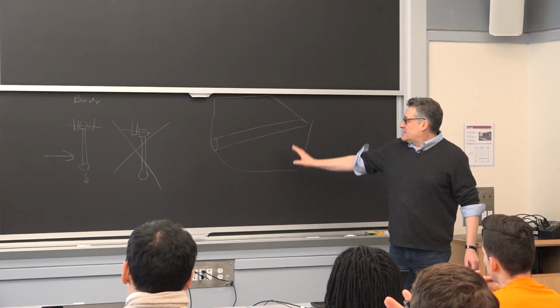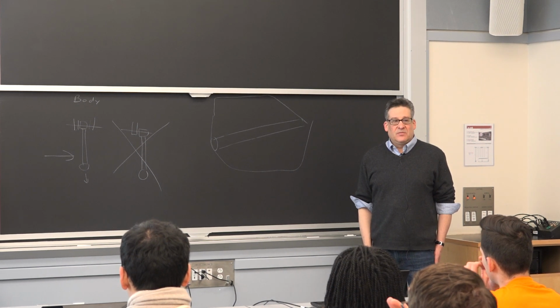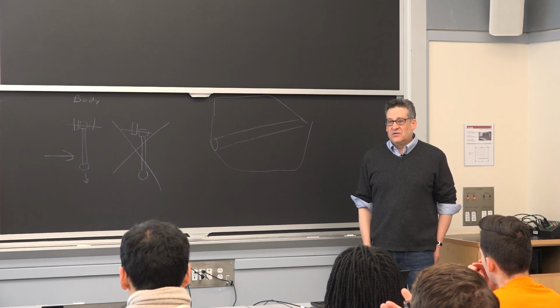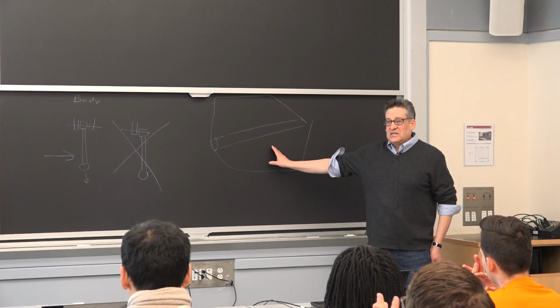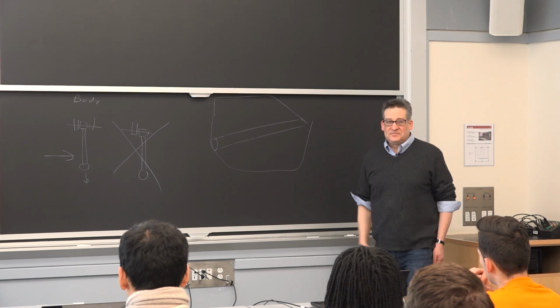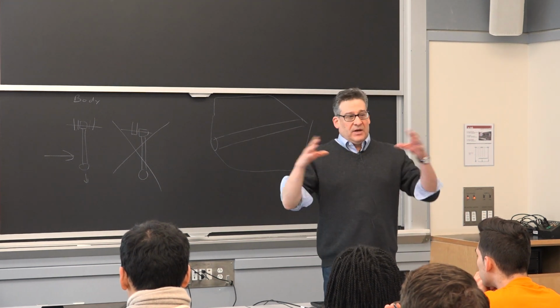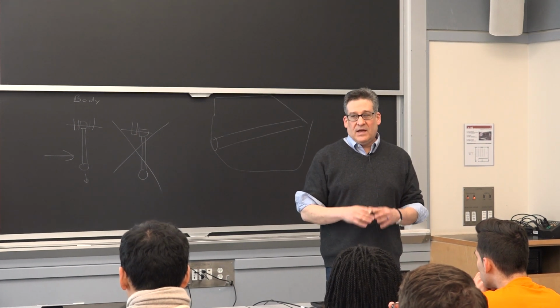So in this application, they have a hollow steel tube in there, and it's typically a martensitic steel. It's very strong steel. But they have to use steel here because they can actually make this side intrusion beam much lighter from steel than they can make it from aluminum. And they use this exact same principle of going to a bigger diameter and a thinner wall in order to keep the weight down.